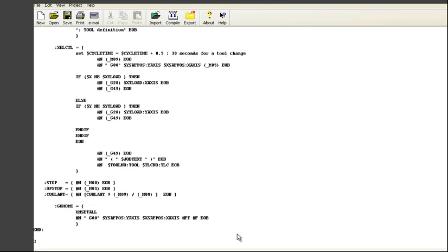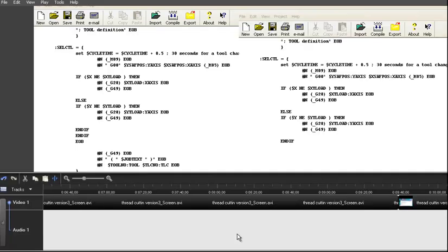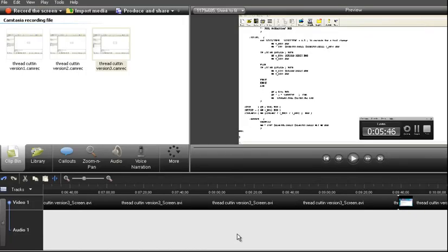And an interesting thing, I specifically told them that I need a post processor for radius mode, and I got one for diameter mode. And this is the first thing that I edited by myself in the post processor: Y scale.